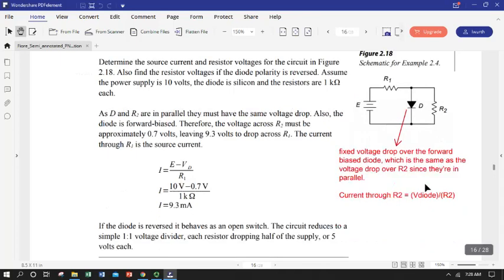So Mr. Fiore walks us through that, but that's kind of the crux of it, is the current through R2. So how do I get the full current? I can go through my node voltages. I can apply KVL, and I'm using this parallel branch as a combo. I start at ground. I go up through the source, which is 10 volts. So my upper left-hand corner is at plus 10 versus ground.